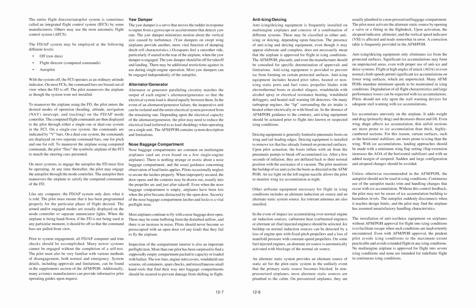The yaw damper should be off for takeoff and landing. There may be additional restrictions against its use during single-engine operation. Most yaw dampers can be engaged independently of the autopilot.